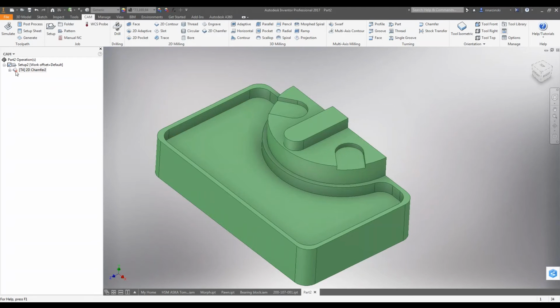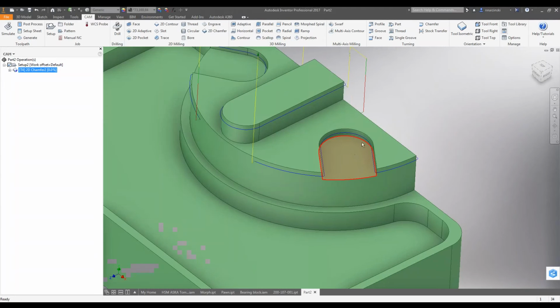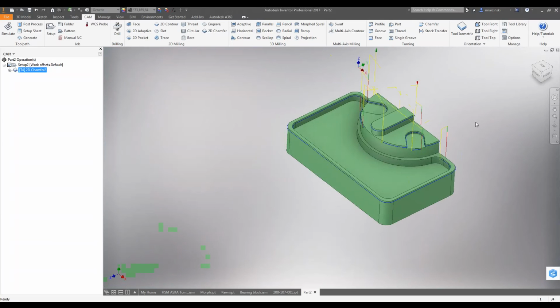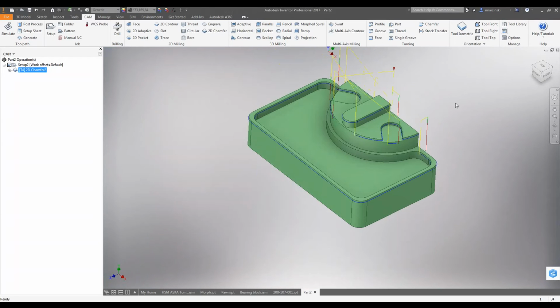And so with that update, you also get a red X over here. The software is smart enough in telling us right here that that toolpath is no longer represented by the model. So you can see what it used to be. So we just need to right-click, generate that toolpath, and it comes through and now updates to that new geometry in the model.